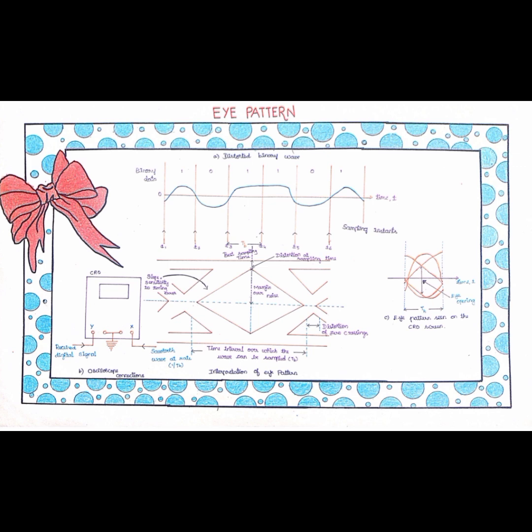The diagram in this assignment shows different eye patterns under noise and jitter conditions. When the eye is fully open, this means low bit error rates and a reliable communication channel. If the eye is closing and errors increase, that is a problem in data transmission.